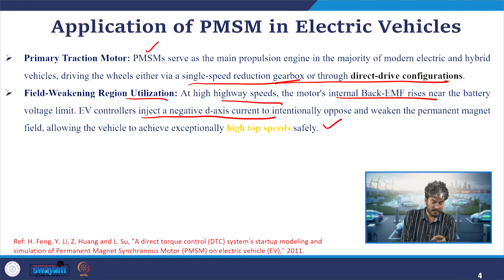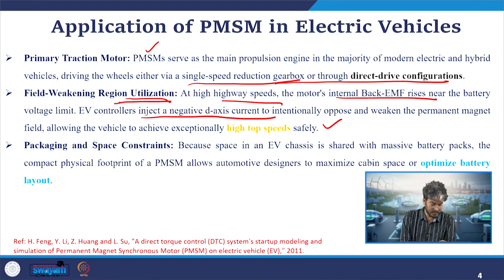Okay, so this comes with a cost. If you go for repeatedly demagnetizing it, it can get permanently demagnetized, whereas in this case we assume that it is temporarily demagnetized, and when we remove this negative excitation, it should come back to its original magnetic state.